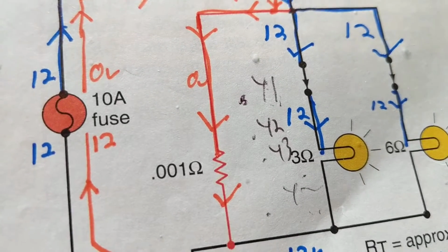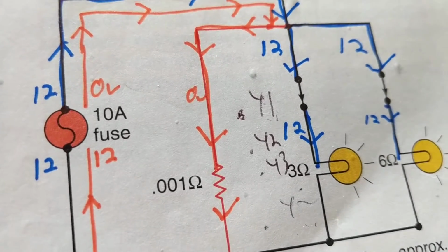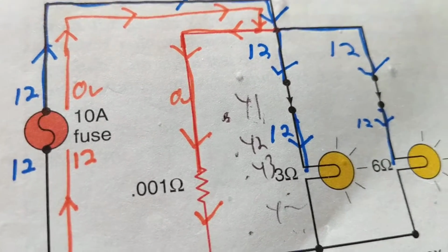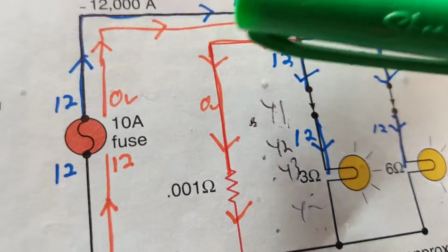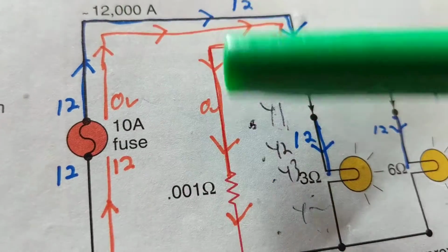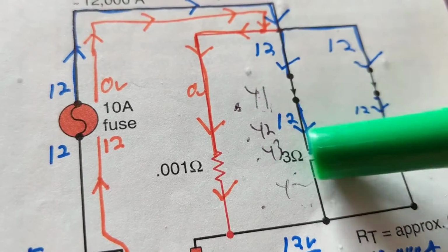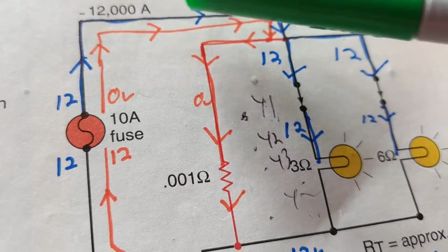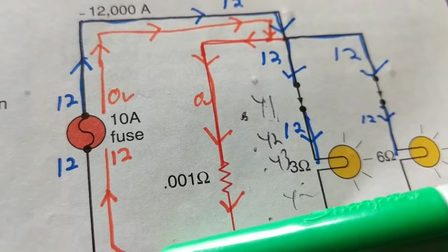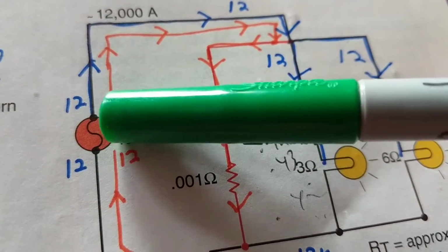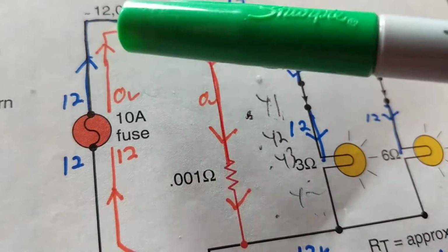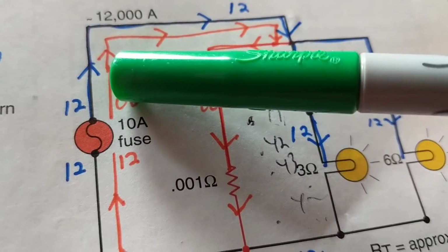If you ever see a booster, the peak amps are like 1,000 amps, right? So obviously, a short across the bulb itself will give us the same result. This will blow the fuse. We have to find the short first before we put in another fuse.